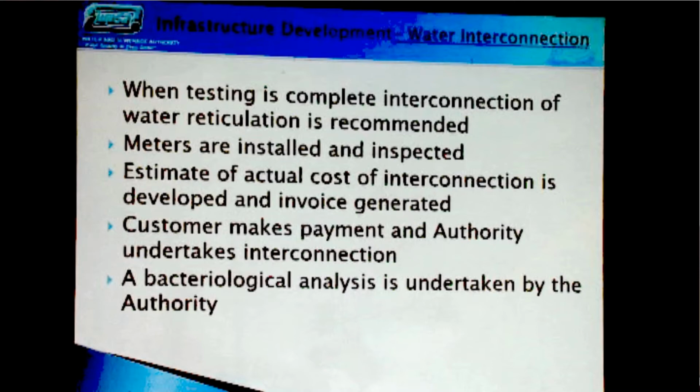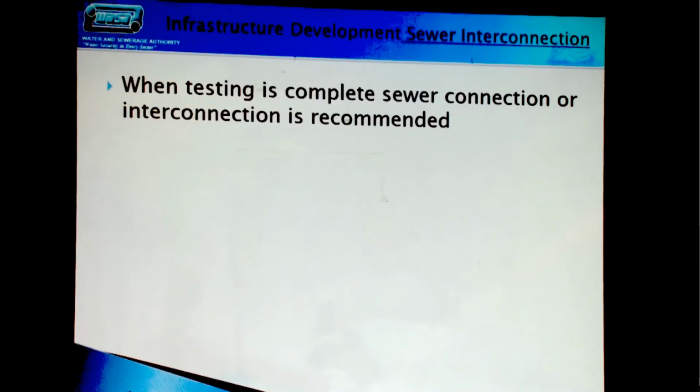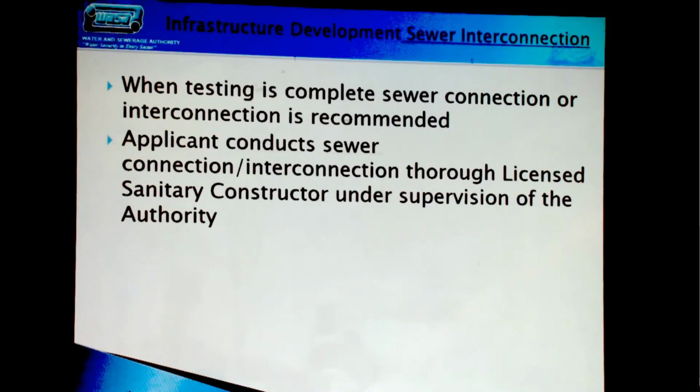We will do a bacterial test and commission the water reticulation system. Where sewer connections are required, we do the same thing, testing of the sewer system. The applicant will conduct the sewer connection under our supervision.